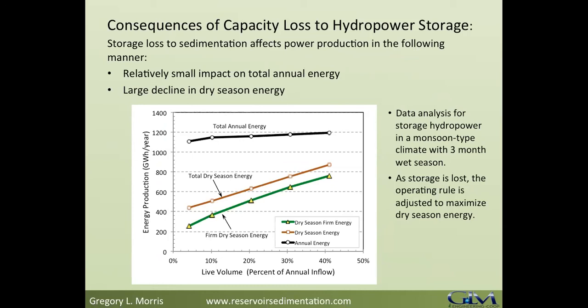Yes, the discharge of sediment downstream, ideally we would be able to have the reservoir be essentially invisible from the standpoint of sediment. Unfortunately, what happens is that the fine sediment, which is not typically what we want from the environmental standpoint in the river downstream of the dam, is a lot easier to move downstream than the coarse sediment.